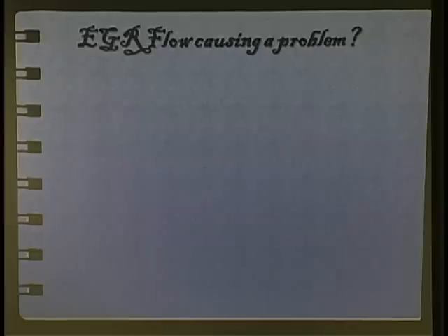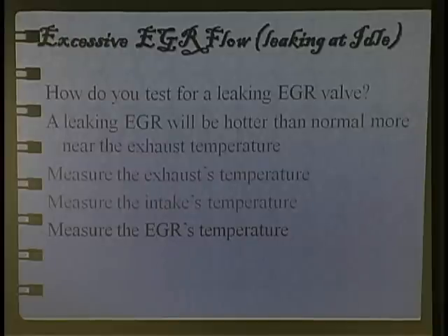So measure the EGR temperature. Which one is it closer to? And I will tell you something. When I've done that with people, what do we want to do with leaking EGRs? We want to put a piece of cardboard in there and block the EGR. And if the problem goes away, we know that's a valid test. I still do it. A pipe plug for Fords. So yes, I want to block it. But the truth is, one day I went, duh. If there's EGR flowing through, it's going to be hotter than it normally should.